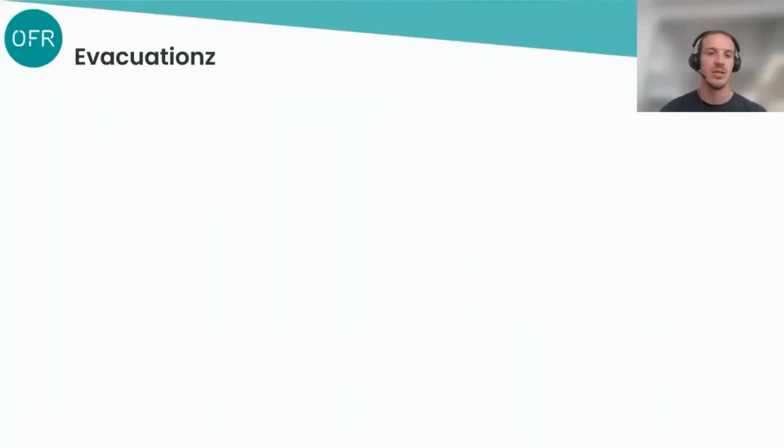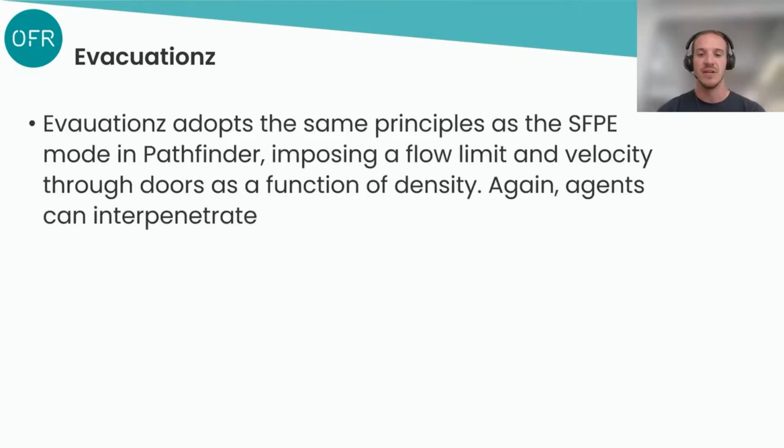The last simulation tool we looked at is evacuations. This is a tool developed by one of my colleagues and co-author of this research, Mike Spearpoint. He's been developing the model over several years. As with the SFP mode in Pathfinder, evacuations adopts the same hydraulic model, imposing a flow limit and velocity through doors as a function of density. Again, with this model, agents can interpenetrate and they're not assigned a physical space in the geometry.